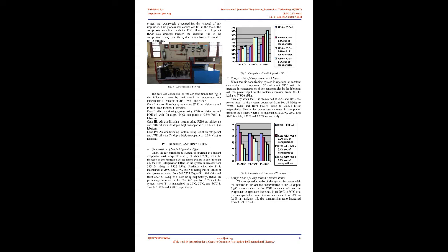The pressure gauges were installed at the salient points of the refrigeration system. Thermocouples were used to measure temperature at various locations of the flow of refrigerant. The power consumption by the compressor was measured using an energy meter. The heater power regulator is provided to adjust constant heat flux and maintain steady state condition.